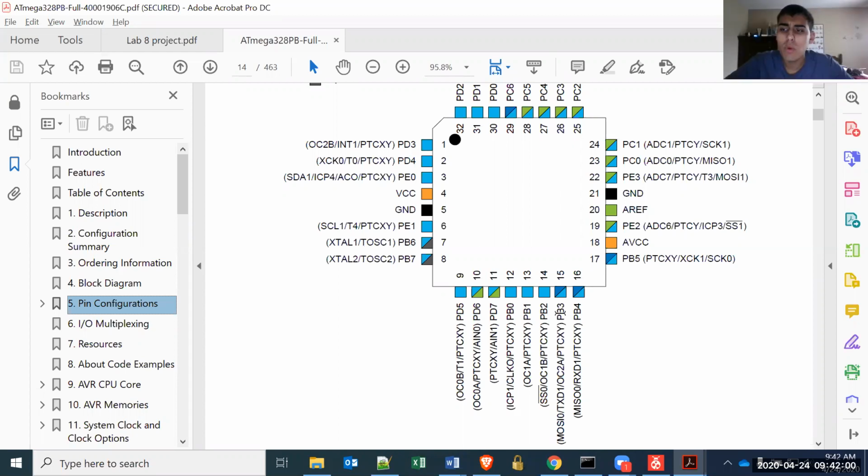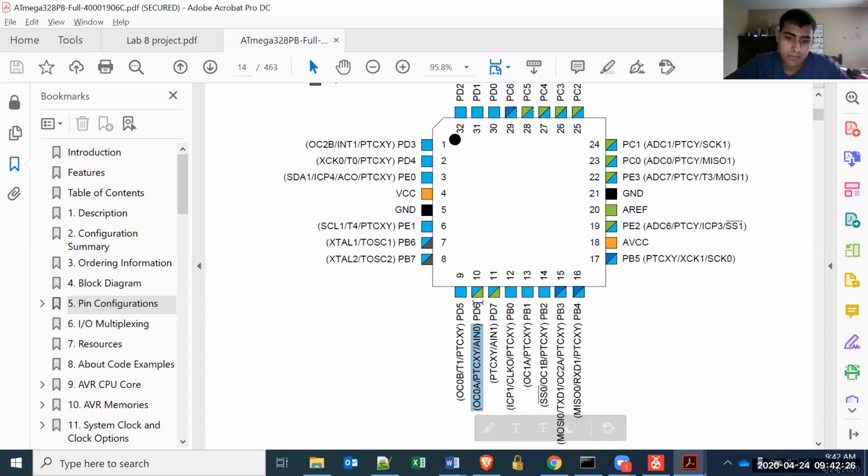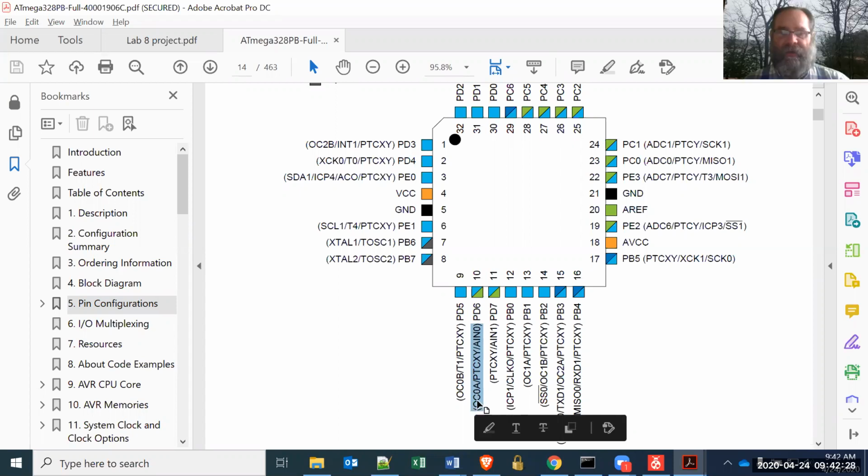What are the ports and bits we set the timers to again? What's the question, Ben? Which ports and bits do we set for the timers again? Okay, well, timer 0 is PD6, or the red LED. And again, you should be able to see on your screen what I just highlighted. Okay, I see it now. Yeah, pin D6, that's timer 0.